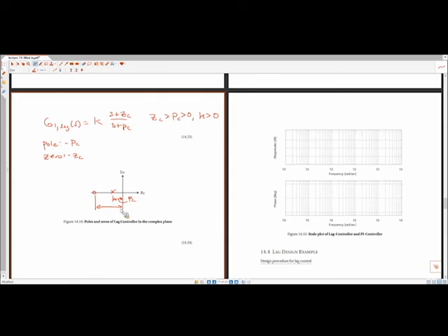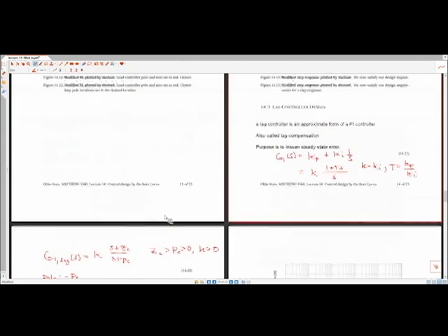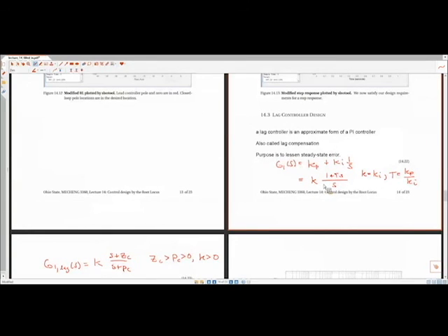Okay. Karsten. So, in the previous one, we defined K to just be Kp. Why do we define K as Ki in this case instead of Kp? So what we're doing here, I think I get your question. What we're doing here is we're trying to find an equivalent way to write this, such that we have a gain out front, and then it has pole zero form. We have just polynomial in the numerator, polynomial in the denominator. So just writing in this form, and it just so happens that by writing this, K is equal to Ki. If you go back to the other example, if we write it in a similar form, that was the term that was the gain out front. So just looking at equivalent forms, nothing more than that.